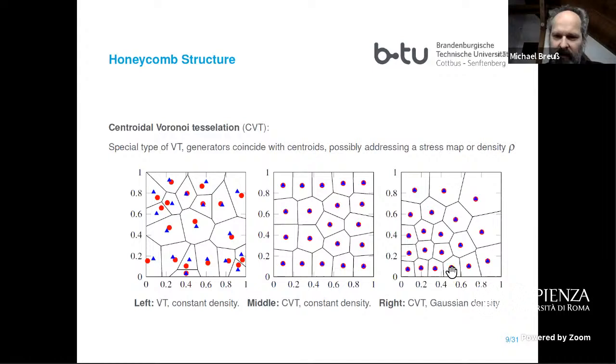In this image, it's still a centroidal Voronoi tessellation, but at the point 0, 0, at the origin, you have put in a higher density as an underlying weighting function, and you see that the Voronoi cells are still looking like an evenly distributed shape, yes? But they are more concentrated. So you get some design freedom. And of course, the other part of the design freedom is how many generators you put in in order to construct Voronoi cells. So this seems to be not unreasonable.